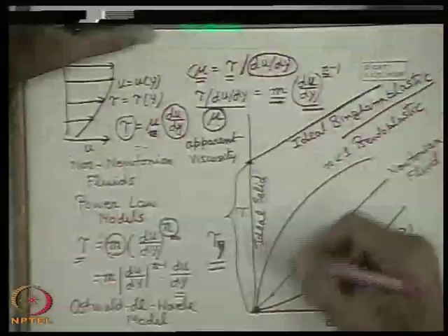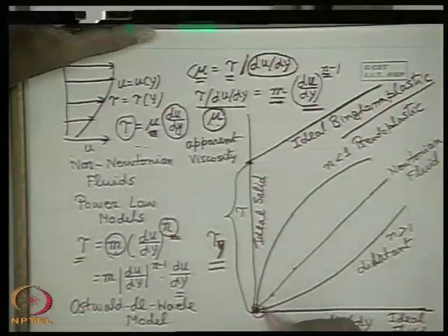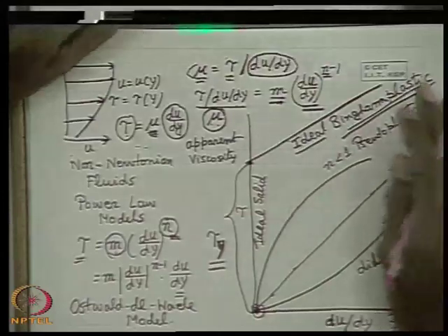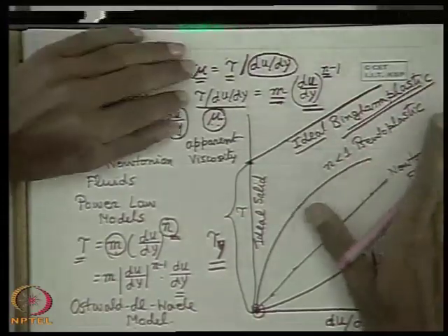That means the shear strain is developed and the flow develops, which means analytically that the stress and rate of strain relationship or curve passes through the origin. Therefore, the classes of substance which do not follow this, that means there is a yield stress, violate the basic definition of the fluid. So for these reasons, the Bingham plastic is not considered as a fluid.